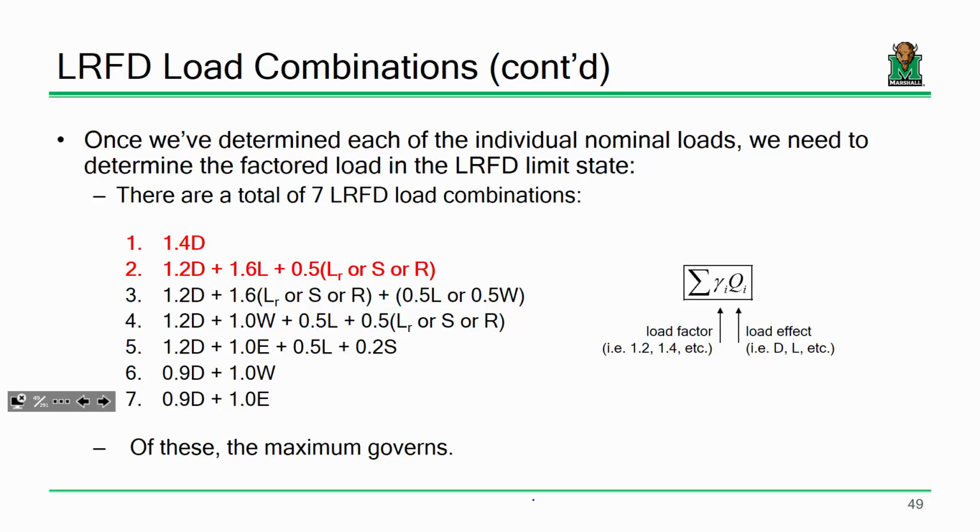Well, if we're talking about the lateral system and like the moment frame or the brace frame or the shear walls or something like that, any moment frame is going to have to resist lateral loads, but it's still going to also have to resist its own self-weight and all the gravity loads that are being framed into it. So, like moment frame elements, like the beams and columns that go into moment frames, are going to have to withstand wind and seismic, but they're also going to have to see dead loads, live loads, and snow loads as well. Does that make sense?